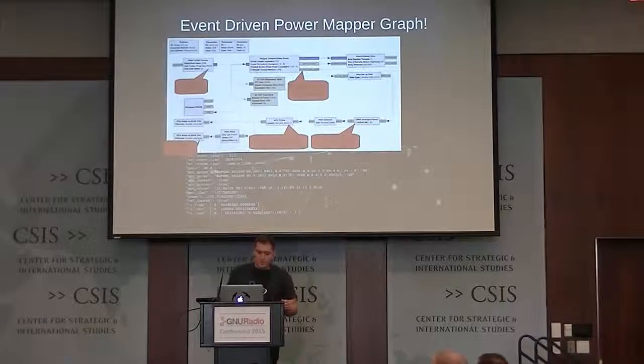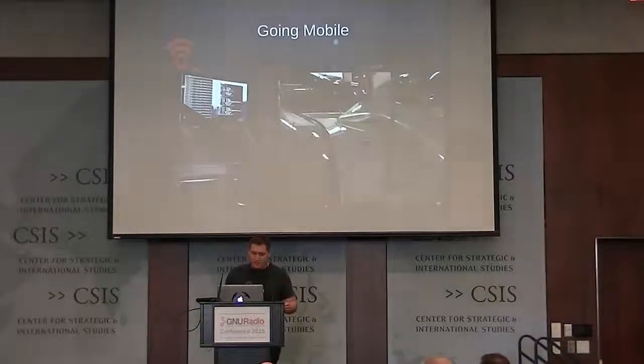So that's what we're doing here: we're triggering every n samples and extracting a chunk of raw IQ. We're then taking an average power over that message, probing the USRP GPS DO to get an NMEA location string, and then tagging that onto the message, and passing it over here to write out to a JSON file. Right. So this down here at the bottom is an example of what a single record would look like. We have a time in seconds, this GPS location, lat long, and an RSSI for the current signal strength of the FM that we're seeing. And so we write this out to a file. We have just this big list of observations that we've made of the broadcast station, and that's it.